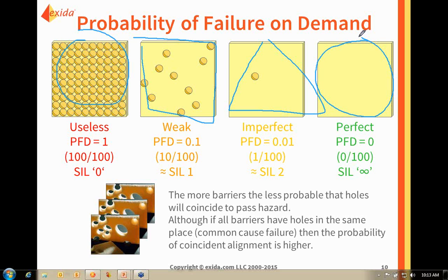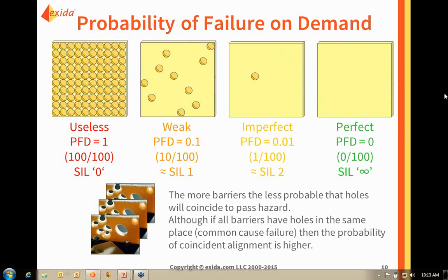Now, I don't tend to believe in perfect. I don't tend to believe that we will have a probability of failure that is equal to 0. So I would like to even consider maybe 1 out of 1,000 or maybe 1 out of 10,000, but at least say, hey, nothing in life is perfect. People can make mistakes. Obviously, the more barriers you have with the lower number of holes, the more unlikely it is that those holes will line up and that your hazard will occur. So that will really reduce that initiating event frequency to something that is more acceptable.